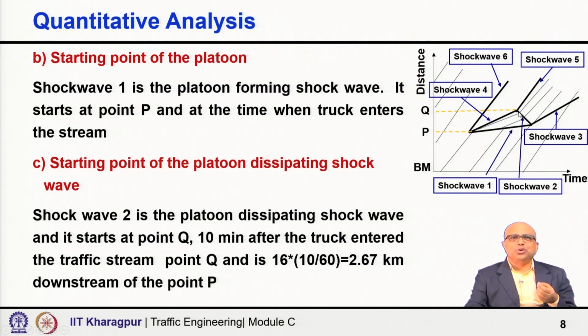When will shock wave 2 start? Shock wave 2 is the platoon dissipating shock wave and it starts at point Q, when the slow moving truck leaves the traffic stream. Then the recovery shock wave, or the platoon dissipating shock wave, will start. And it starts obviously at point Q, after 10 minutes of the truck entering the traffic stream at point P, right.